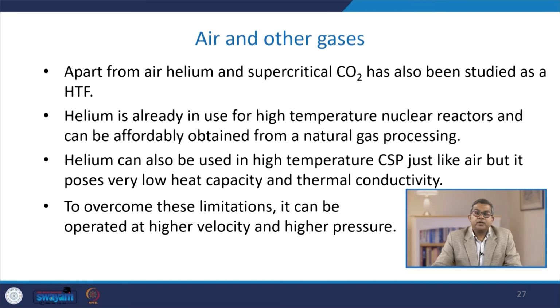Helium can also be used in high temperature CSP just like air, but it has a very low heat capacity and thermal conductivity. Now, these are several limitations which need to be addressed. To overcome these limitations, the entire operation can be run at high velocity and high pressure.